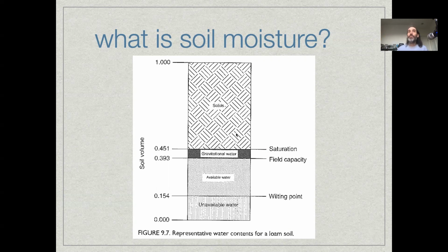going down vertically. And in any of those cubes of soil, you've got a mix of things going on. So you have a mix of solids, gases, and liquids. The solid part of soil is the obvious part, because we think of soil as a solid thing. But in practice, various soils are usually only a little bit over half composed of solid material: our clays, our sand, our silts, and rocks. But there's a lot of pore space in your average soil.